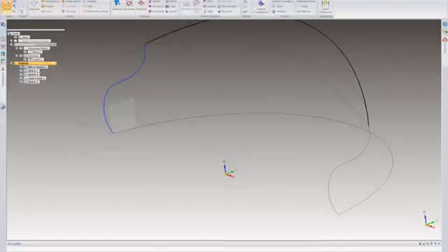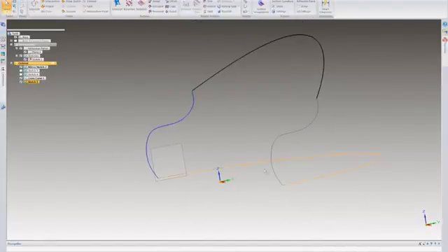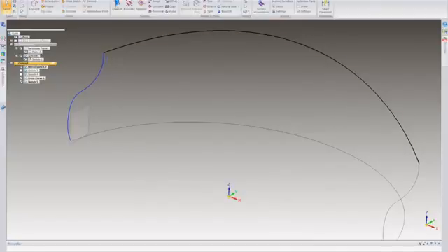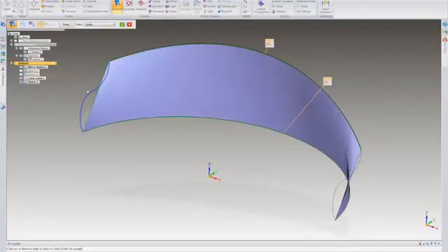All right, so I'm going to go ahead and create a blue surf now. Now they have the curves. I have a 3D curve in space, and of course I have a flat curve, and of course I have a mirrored sketch of the synchronous geometry. So I'm going to go here and create a blue surf now. A couple different ways. I can go either from this curve to this curve, or actually from this curve to this curve. So in this situation, I'm going to go ahead and let these guys be the guide curves. So I'm going to say I want this curve to go ahead and match this curve.